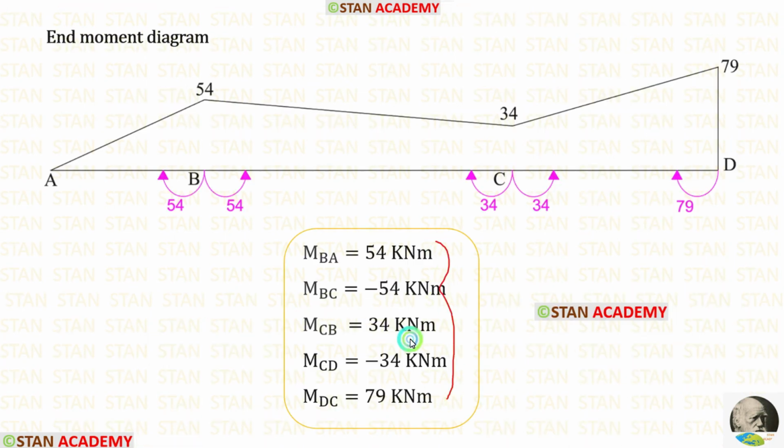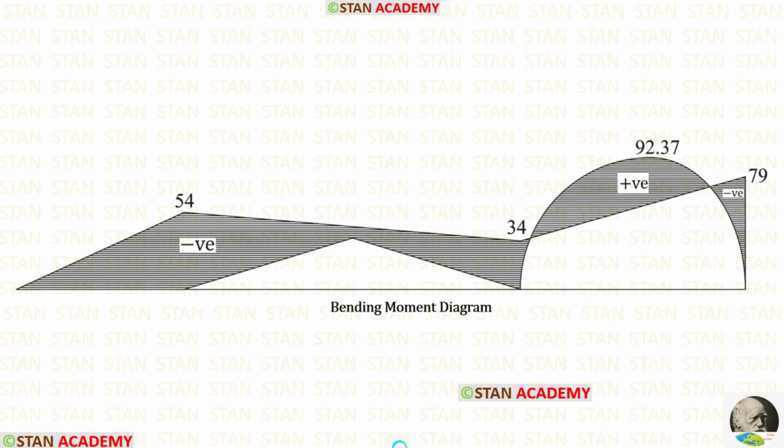Now, using the end moments, we can make the end moment diagram. Then we have to combine the end moment diagram and free moment diagram so that we will get the bending moment diagram. Now we are going to end this session.